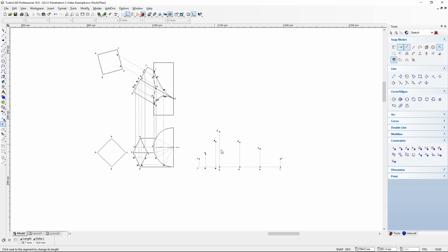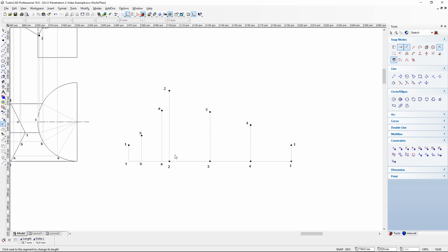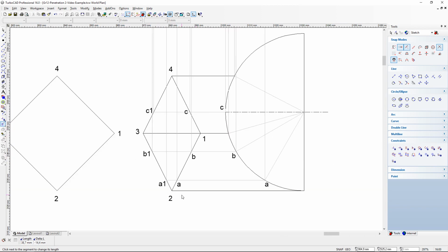So what I want to do is now determine what reference points I need between 2 and 3. So let's just see, on our top view we have from 2 to 3, A1 and B1. Now obviously I can't measure these heights here or lengths here on the top view because the prism is slanted here, therefore it does not give me a true length.